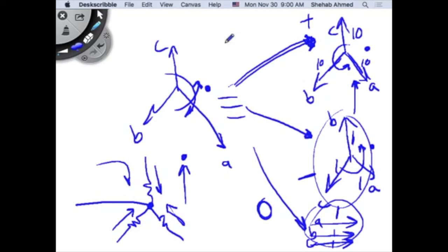You can also generate a rotating MMF with two phases 90 degrees apart. That's how single-phase machines operate. You put a voltage on one phase and a voltage 90 degrees apart. If you've played with motors in a fridge, you would typically have a starting capacitor. You talked about single phase motors in 338, and you remember Dr. Haytham putting a starting capacitor in there, right? What was that capacitor doing? Yeah, it was creating this phase shift because you only had a single supply.